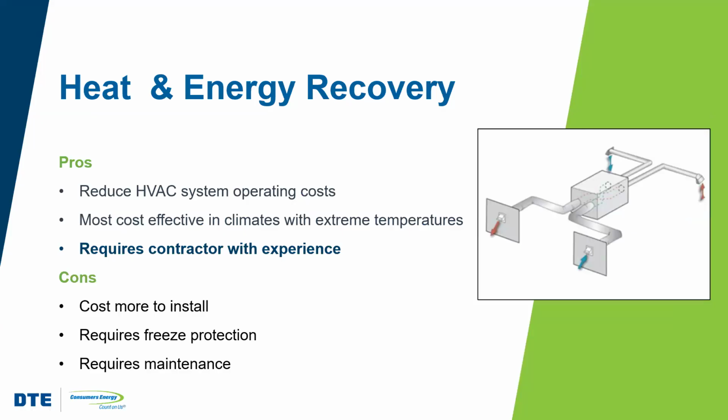We talked about the heat recovery. So, some pros and cons of those heat recovery units. They help to reduce HVAC costs, right? Because if you can exchange thermal energy between those two airstreams, if you can extract residual heat in the air that you're going to be exhausting out of the home, and you can use that heat to preheat air that you need to heat up into the home, then the furnace doesn't have to put in as much heat, or vice versa if you're doing cooling, right?